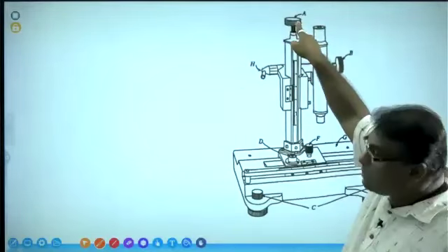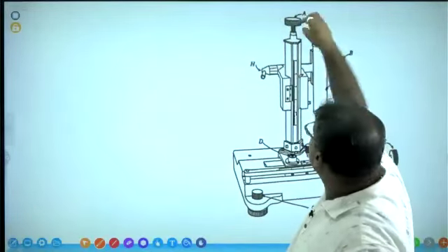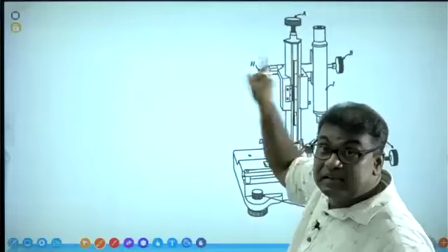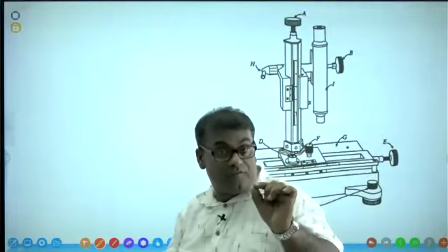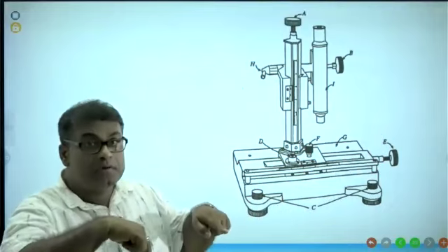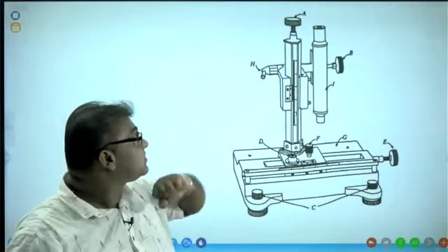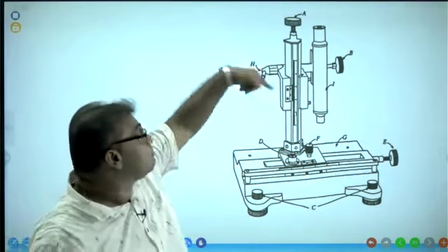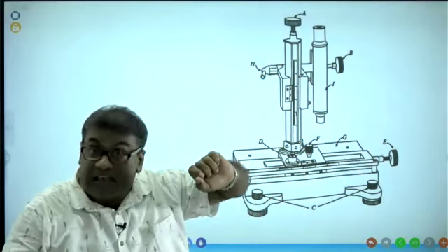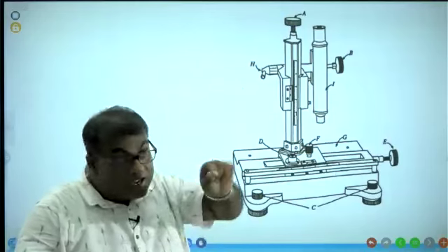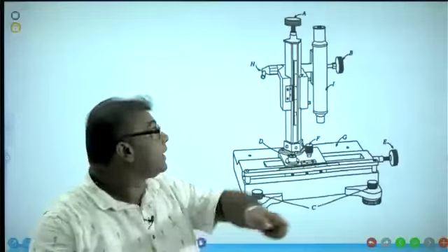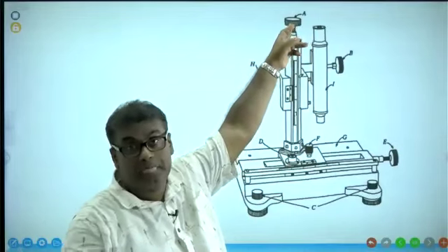Before operating this one, the screw called the rough vertical adjustment screw, which is behind the traveling microscope and not seen here, should be well tightened. You have to tighten it well, not release it, before operating A.